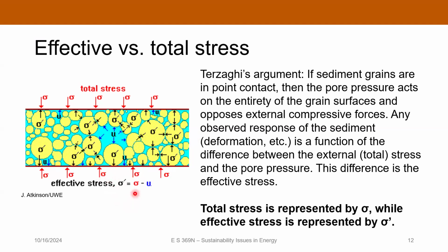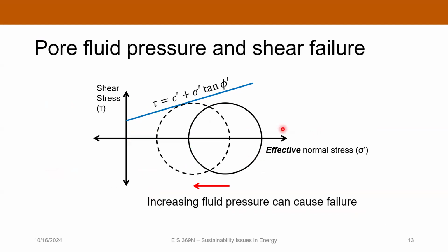And that is simply the total stress minus the pore pressure. This is an important point because when we are drilling and we have a drilling fluid in the borehole, we are changing the effective stress based on what the pressure in that drilling fluid is.